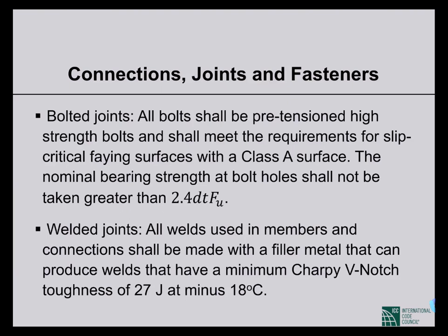So the filler metal, the weld metal, has to be tested. And if we have a manufacturer certificate, that is okay. But if it doesn't carry any certificate, then we have to go for this Charpy V-notch toughness test. I think many of you have experience of this testing in the SM lab. We do this testing in our second year, level 2.